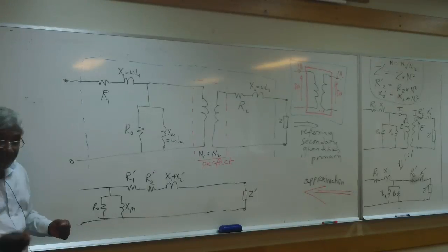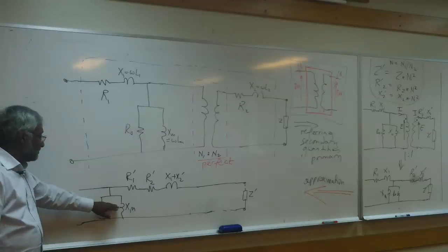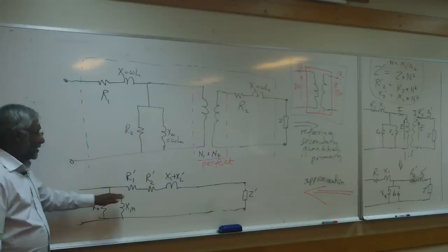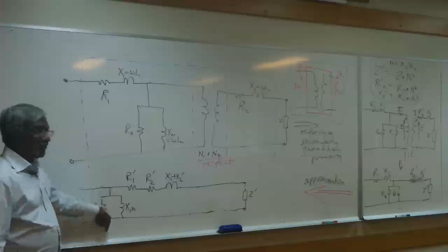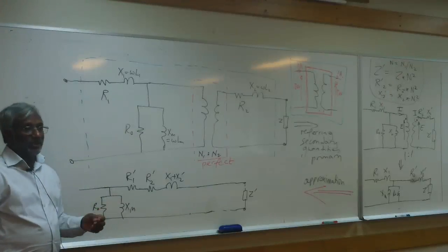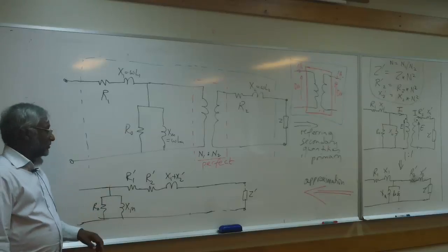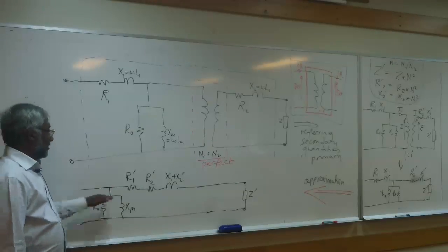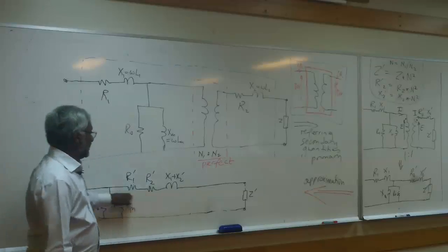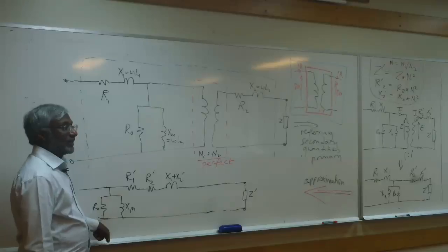So, as you said quite correctly, that is okay to do because these impedances are much higher than that one. The no-load current goes through here, and no-load current of transformers would be typically only a few percent of the total current. So in practice, at full load, the current that goes there is a lot more than the current that comes here.